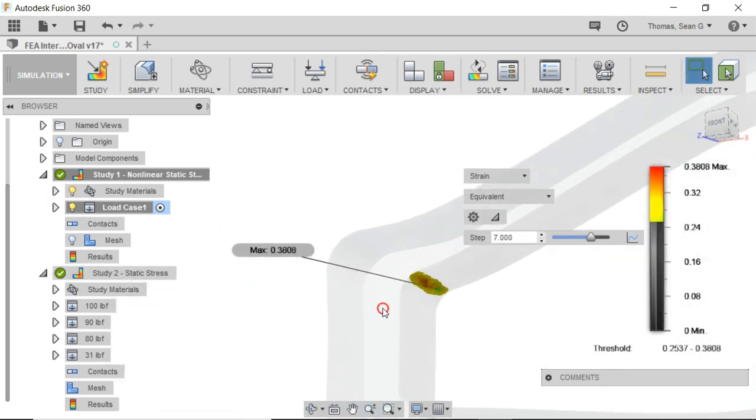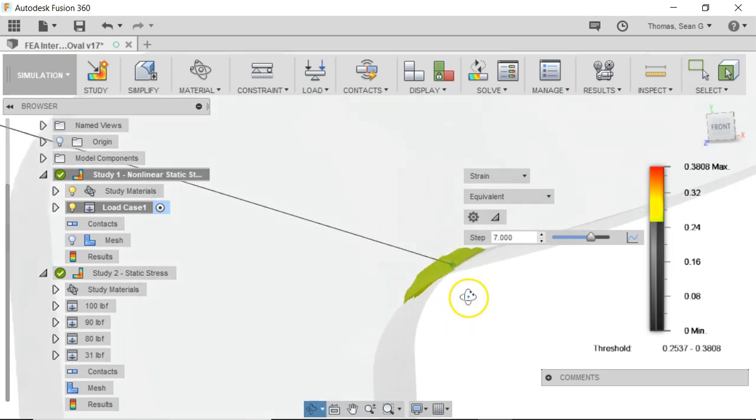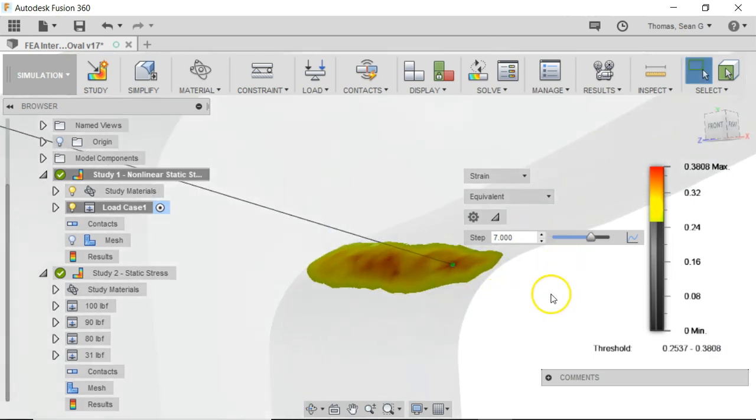our threshold of 0.25. It actually doesn't even go much into an element. This is really a surface. I don't think it'll fail at 70, but this is the first point at which I would say we have a risk of initiating a crack. If we left it at 70 pounds for a long time, we would probably get creep and ultimate rupture, but